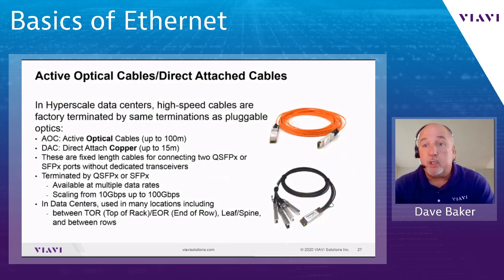Most optics have an LC or an MPO connector on them, which you connect up to a fiber. Again, you want to ensure the fiber's clean before making the connection, but then you can use any variable length patch cables to connect up to your line under test. Some SFPs have fibers permanently attached to them, or copper permanently attached to them for that matter. They're called AOC cables when they're optical, and DAC cables when they're copper. So these present special challenges when you're testing because you can't measure loss across the fiber. You don't have access to the fiber for testing. So in order to test these, you need to test SFP cage to SFP cage, and test equipment can be used for that as well, as long as it has 2 ports on it. We're going to demonstrate that to you shortly too.